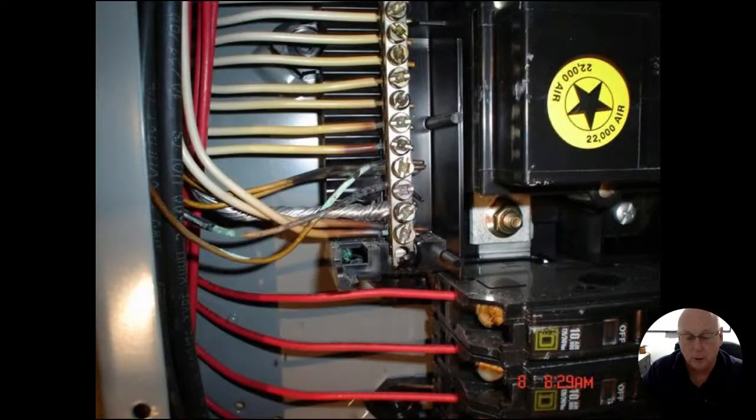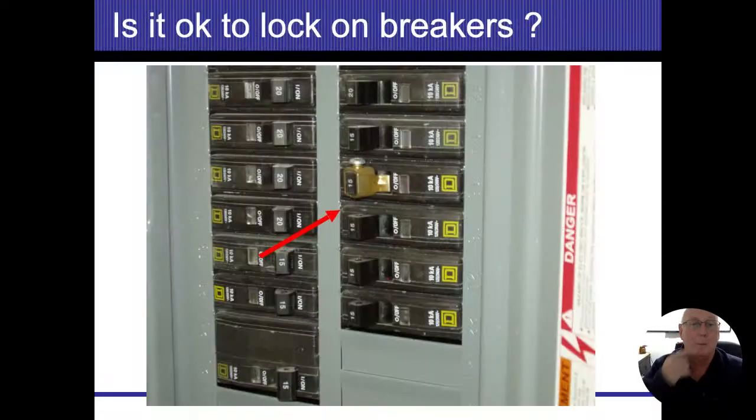This one we saw earlier. Anytime I overload the neutrals, and it is possible to overload neutrals, if I'm sharing that neutral and they're both on the same phase, I can easily run too much electricity than what it's designed to carry. And also, if those wires are loose, they will create a series arc, and that arc will cause the insulation to melt and burn, just like this. So there's more than one reason, I guess, is where I'm going.